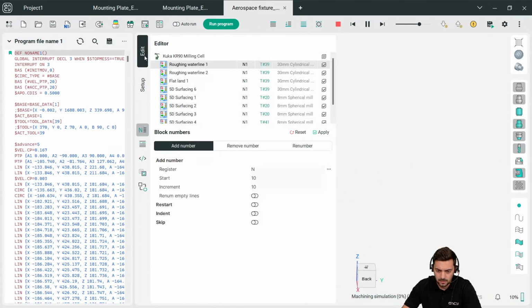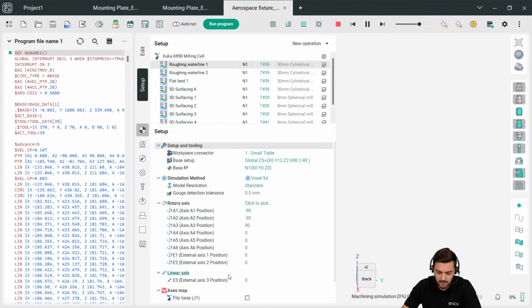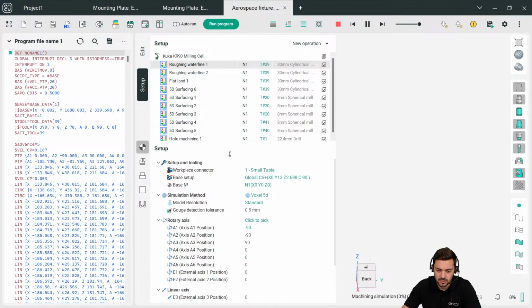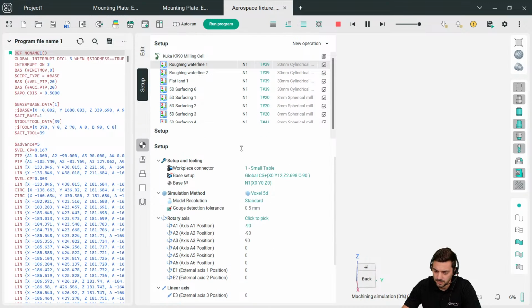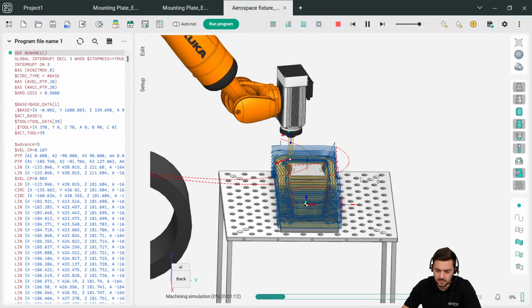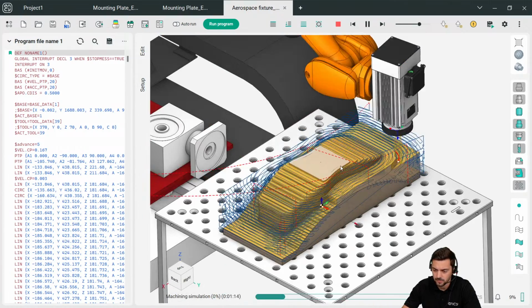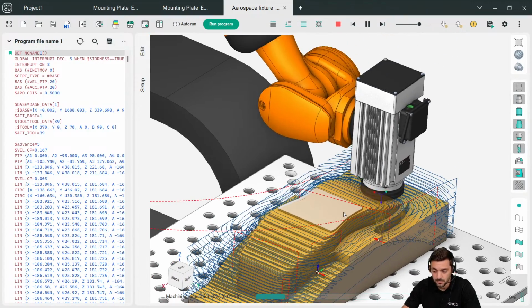In case you are interested, do we have a robot axis map here? No, we don't have it. So you can still make some flips, for example, of the joints, or make some minor changes, but you don't have a robot axis map here, so you cannot optimize robot kinematics. This is part of ENCY Robot and the part of robot programming, actually, not the simulation, from our point of view.